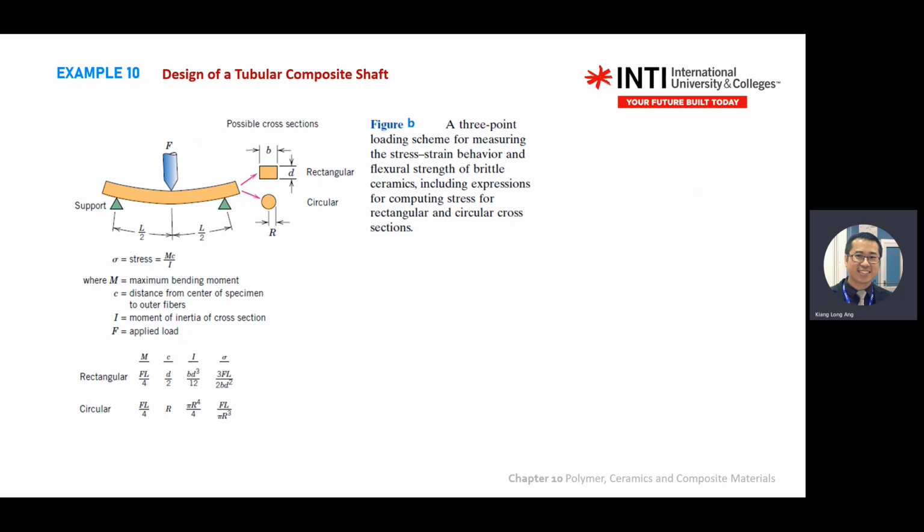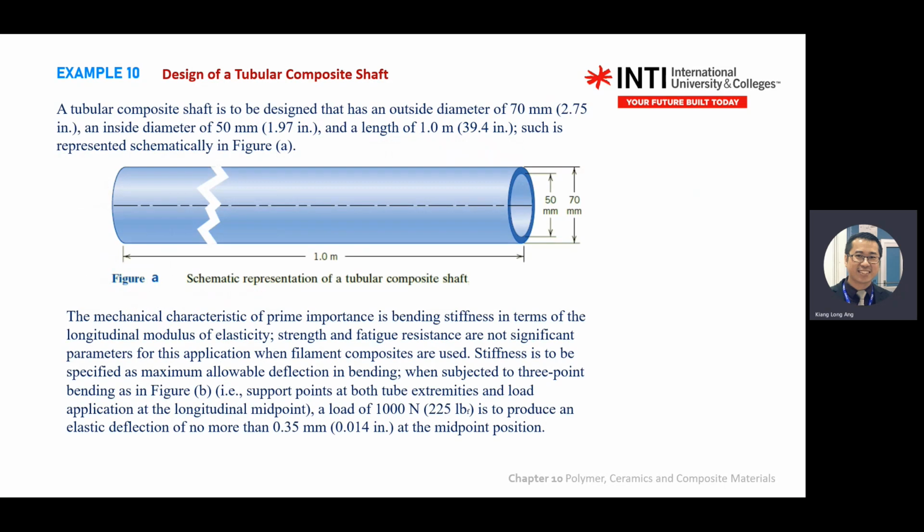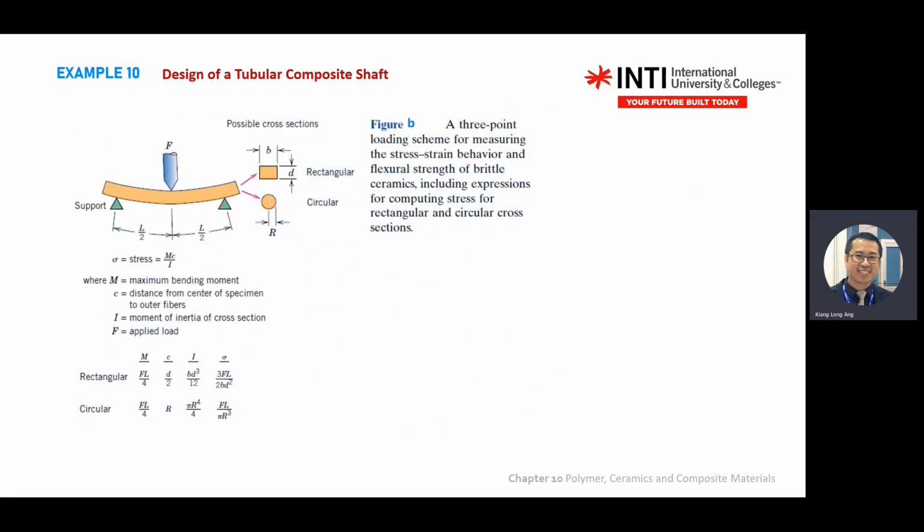So it is simply supported, and there's one force at the middle, and there's an equation to use. The stress to calculate this kind of deformation uses Mc divided by I. So there is an Mc/I stress value here. It depends on the shape that you have. The shape we have is cylindrical, so we are using this equation.